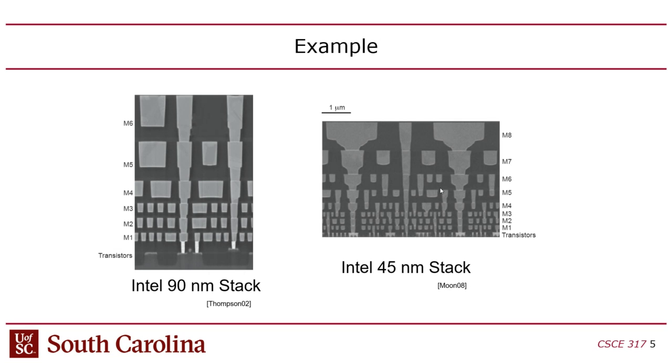It turns out that when they originally designed it, they had limited metal layers, and they couldn't design a 3-address architecture because they didn't have enough wires to connect the 2 operands and keep them separate from the destination. They couldn't get enough wires in and out of the register file. So internally inside the register file, they had to make the first operand also the destination, because they just didn't have enough wires to connect everything.